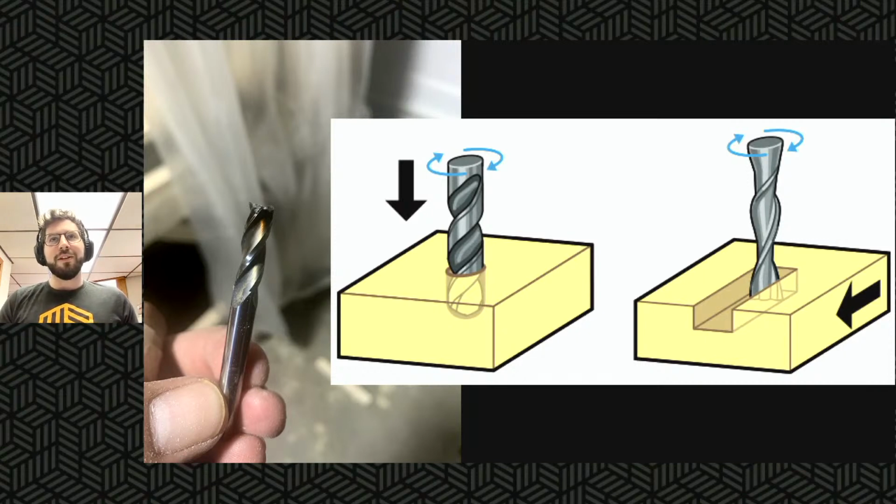So you can see the image here. The bit on the far left is an end mill that's kind of been burned up. It has some discoloration there. It might have plunged into material a little too slowly or too many times, and it doesn't do the job of a drill bit. We've heard about this. Let's watch this video and learn a little bit more about plunging.